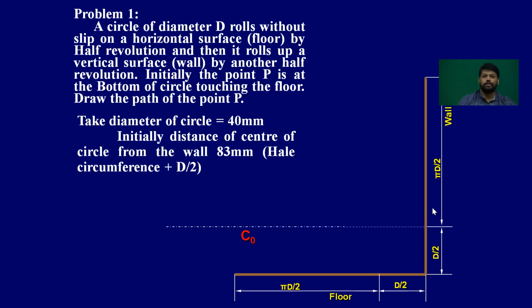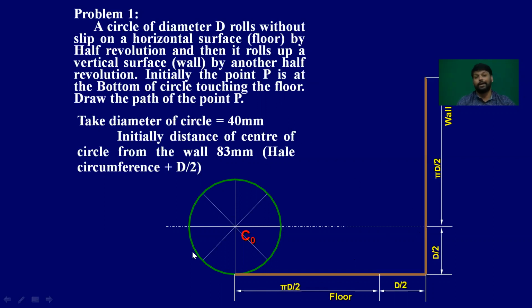Now here, first we need to draw a circle of radius 40 mm. In the previous case, when we saw the construction of the cycloid, we took 12 points, dividing the circle into 12 equal parts. Why we made that is, when you divide into 12 equal parts, we divided the entire rotation, one revolution, into 12 parts, so that you got the 12 points. You can easily connect all those 12 points. But here, because it is a complicated problem, we simplified it.